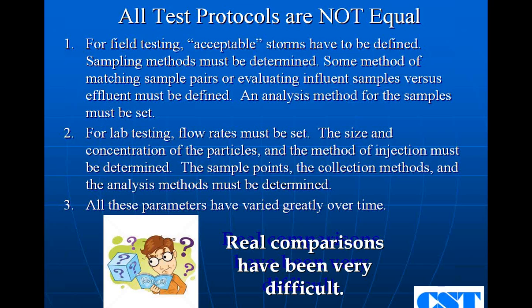If you tested my device with 20 micron particles at a high flow, I would probably score a 2 or 3% removal rate. Tested with the 2,000 micron particles that one fellow did for self-testing, I would be a hero. I'm 100% removal at all flows, and we could declare water quality finished, and everybody could go home. So size and concentration of particles is important.